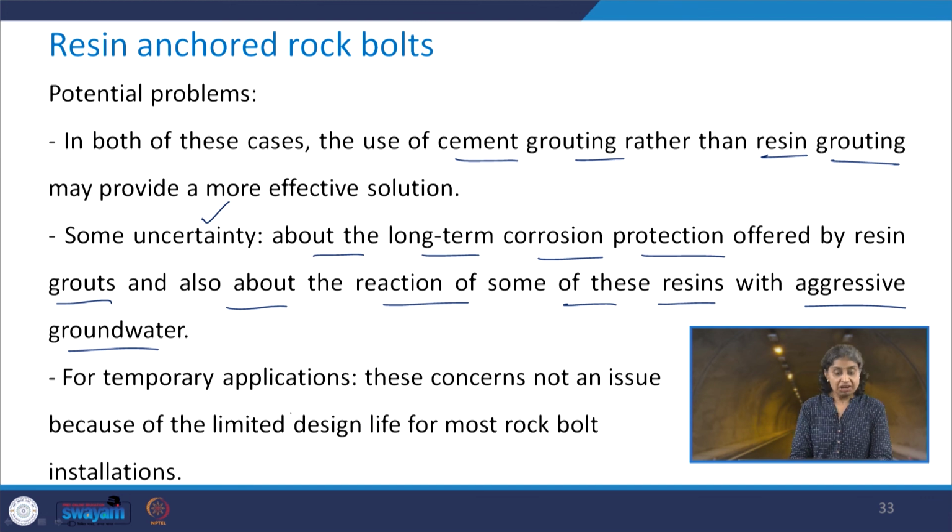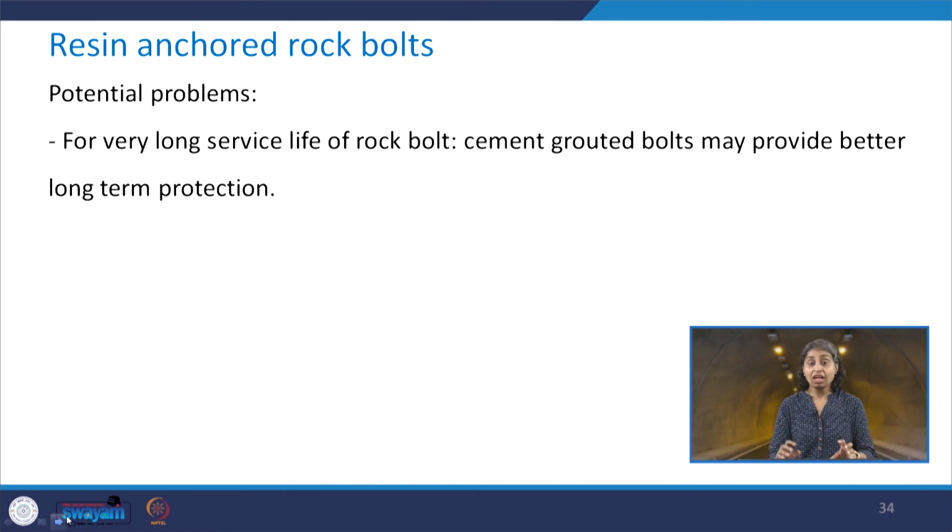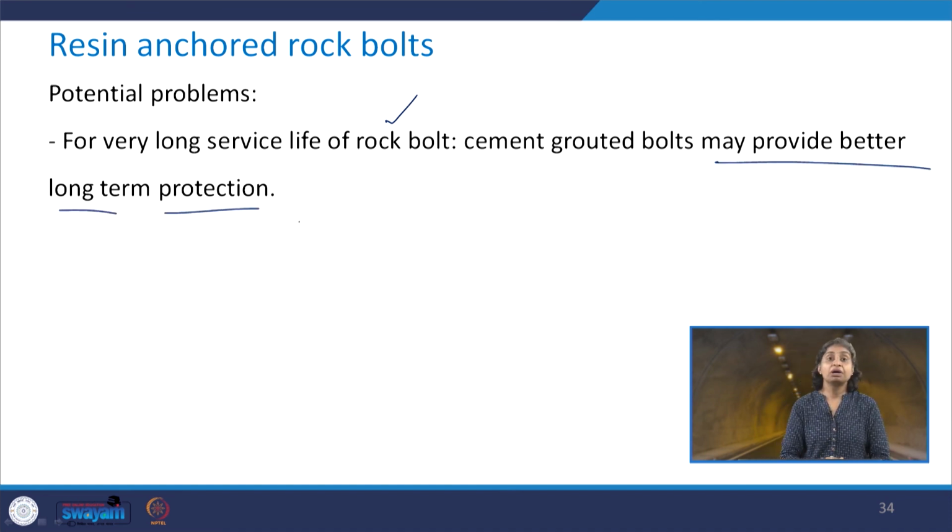As far as temporary applications are concerned, these concerns are not an issue because of the limited design life for most rock bolt installations. However, for a very long service life of the rock bolt, cement grouted bolts may provide better long term protection as compared to resin anchored rock bolts.